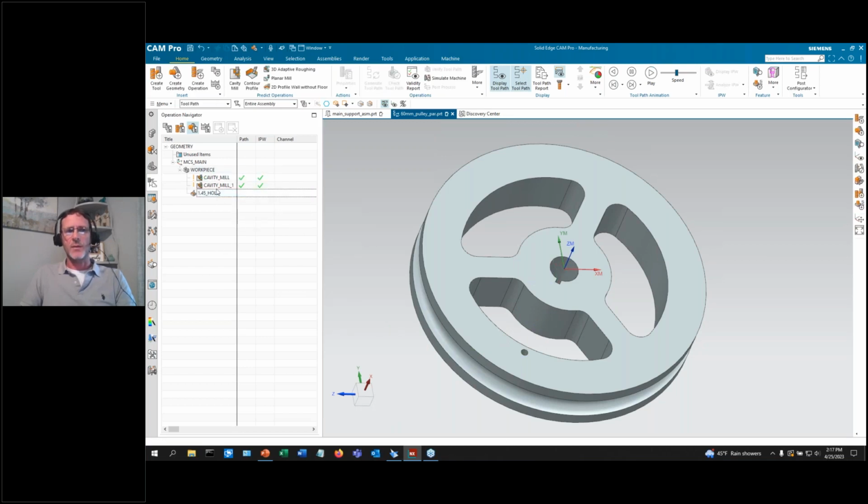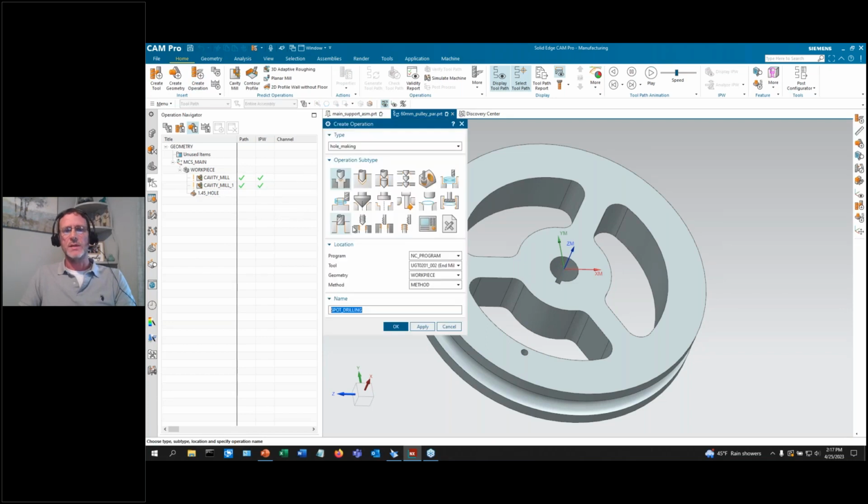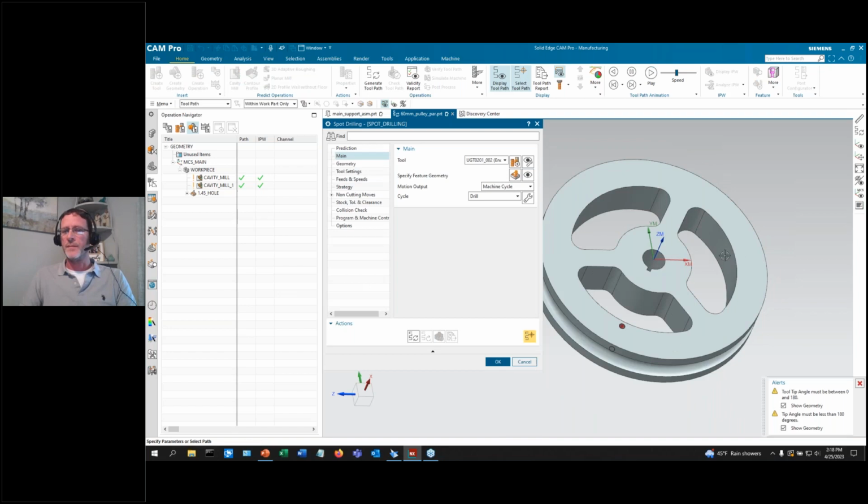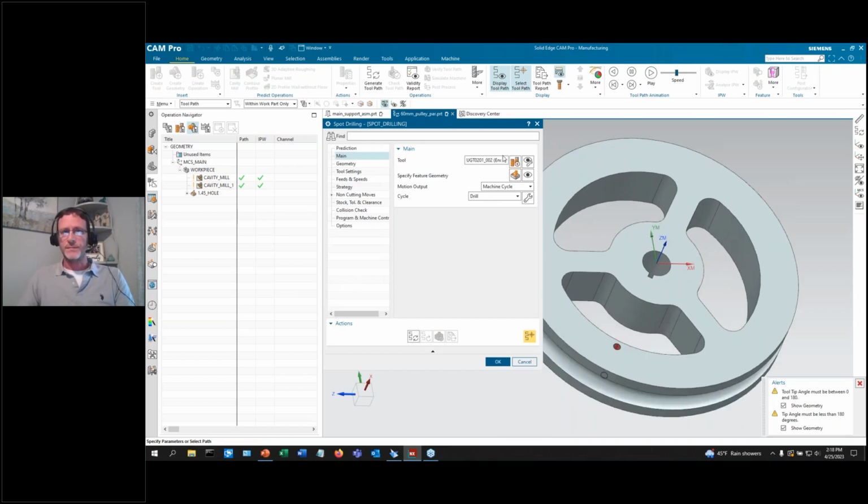Now if I want to program this, I simply select the group instead of the geometry on screen. So now I don't have to select on screen at all. So if I had 30 of those holes that took 6 tools to create, then this is a much quicker methodology of doing this. And we can do the same with milling. I could have chosen these as cut areas and selected them instead of selecting on screen.